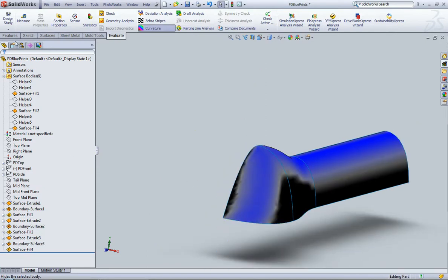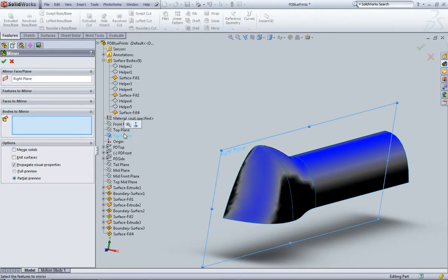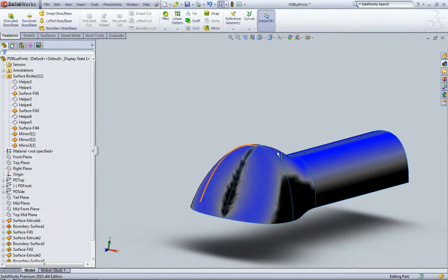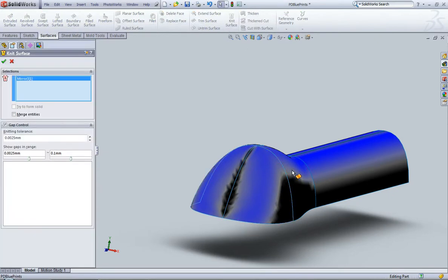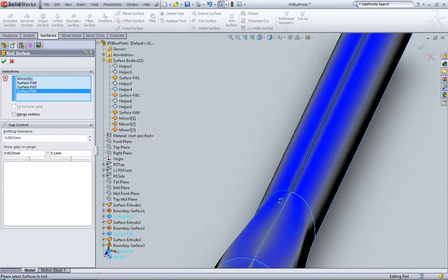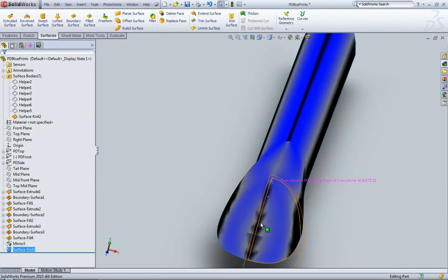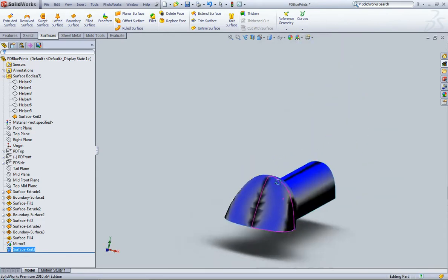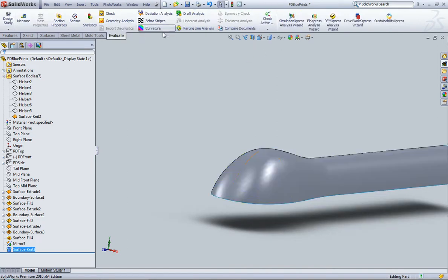And just like we did before, I'm going to mirror this across. One thing that I like to do, it might be overkill, is I'll mirror these, knit them together, save the file, and probably go in and do a couple quick renders. You can see here we've got this white section, and then it transitions into this. The curvature is changing quite a bit. A render, depending on the environment you pick, will really bring out a lot of issues in surfaces.